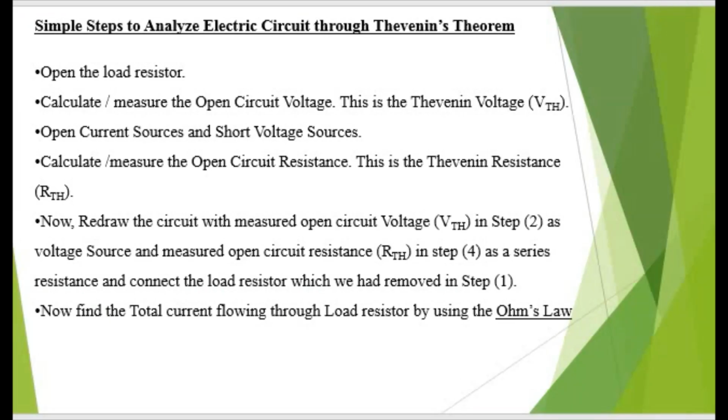Simple steps to analyze an electric circuit through Thevenin's theorem. Open the load resistor. Calculate, measure the open circuit voltage. This is the Thevenin voltage, VTH. Open current sources and short voltage sources. Calculate, measure the open circuit resistance. This is the Thevenin resistance, RTH.